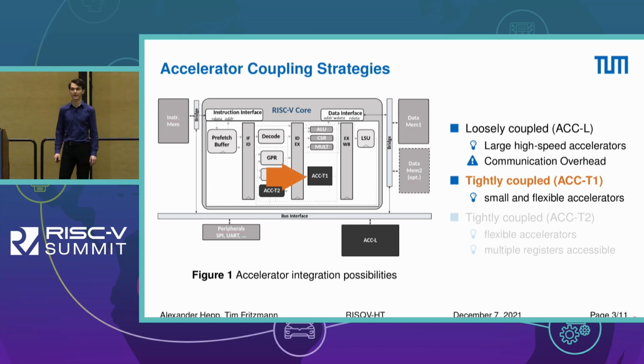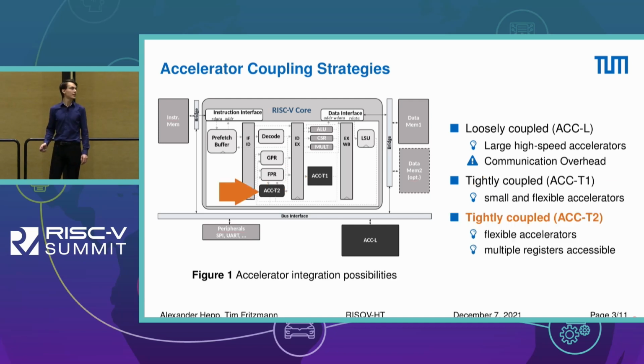of this pipeline. If we want to have access to more registers of the CPU, because we need more data space, for example, we have a hash algorithm that has a large state space, then we would want to have an even more tightly coupled accelerator that would then be put into the ID stage already. In this case, for example, we had a Keccak accelerator sitting in the ID stage, so for a hash algorithm to perform on the complete general purpose instruction set, and in addition, in the floating point instruction set, completing then 128-bit of Keccak state space.